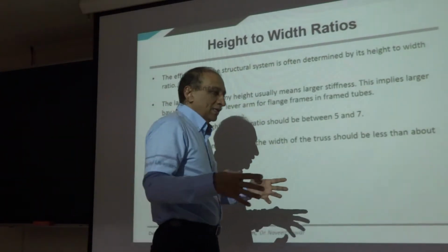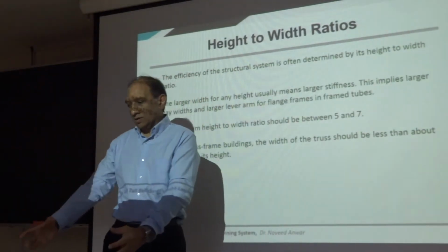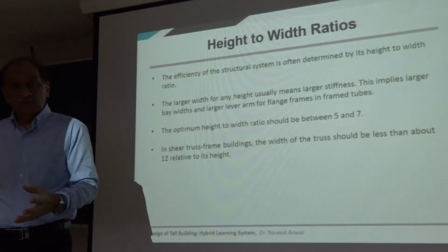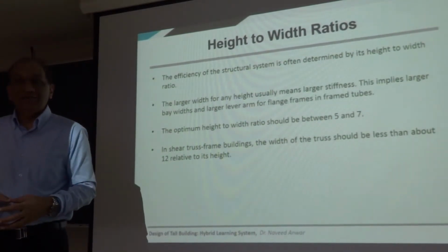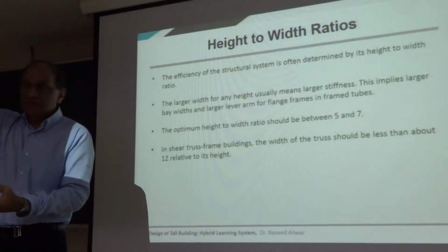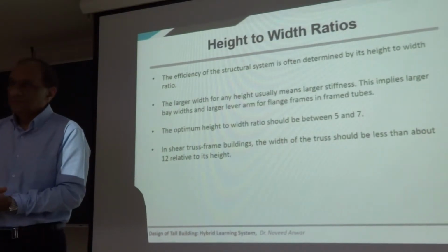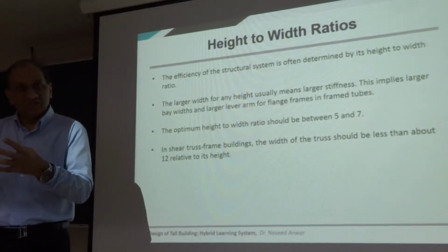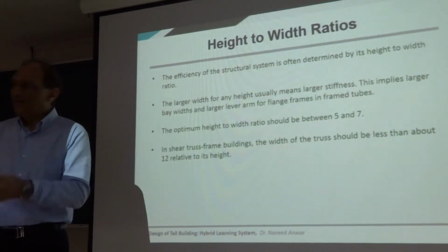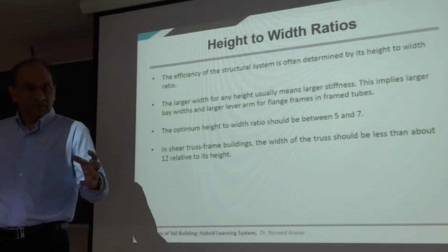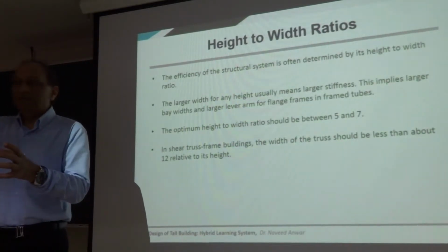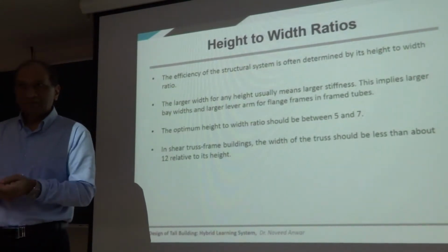In China, what they do is that they not only start with a column at the ground floor which has the highest concrete strength and highest reinforcement, they also put a steel column inside and make it composite. And gradually they take it out as they go up. So they make a composite column with a steel section, a steel column inside a concrete column with reinforcement, with high strength, everything they can put. So the column size will be small, right? And then as they go up, they keep taking things out.